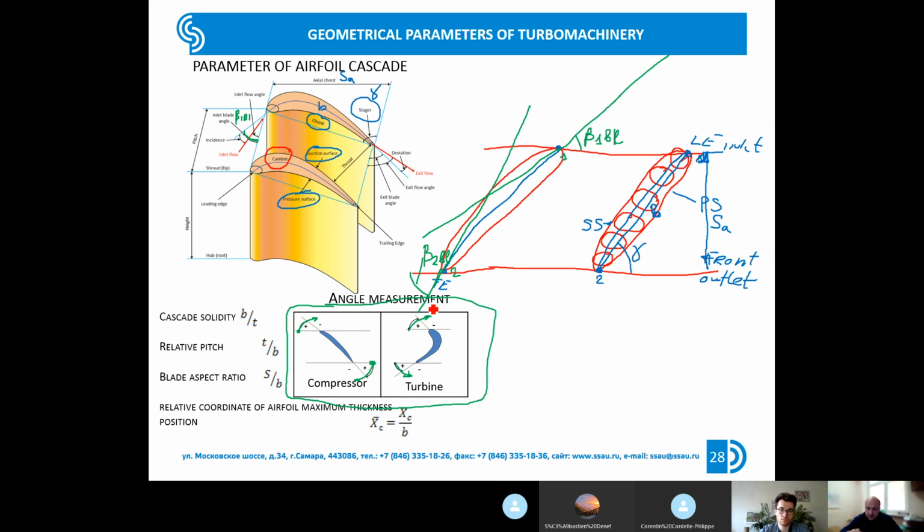Because you live in Europe, you will likely use English textbooks, and you need to pay attention here because the formulas could be changed if you use English and American turbomachinery books. Usually in English and American turbomachinery schools, angles are measured from the axial direction, like this.